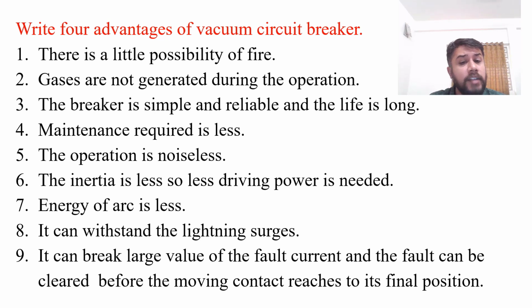The inertia is less, so the driving power required for this breaker to open is very less. Energy of the arc produced is very less. It can withstand the lightning surges as well, so it can be used for higher values of voltages. It can break large value of fault current, and the fault can be cleared before the moving contact reaches its final position.